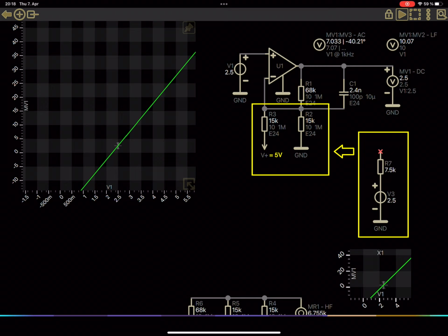However, sometimes it can be helpful to do it anyway as an intermediate step to get a better understanding of the circuit. For example, by doing so, we have the opportunity to verify if the required reference voltage lies between the available supply voltages. This, of course, is required for being synthesizable by a voltage divider.